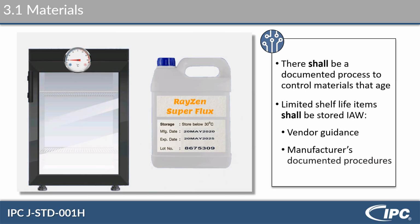Materials, there shall be a documented process to control materials that age, flux and solder and things that have an expiration date. There needs to be a process in place that controls that, so we're not using expired materials in production units. Limited shelf life items shall be stored IAW, which is in accordance with vendor guidance, so who you buy them from, and the manufacturer's documented procedures.